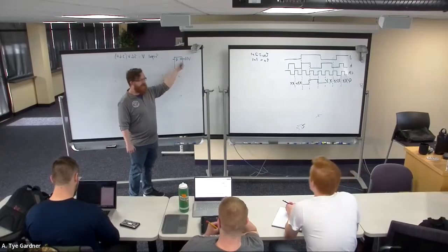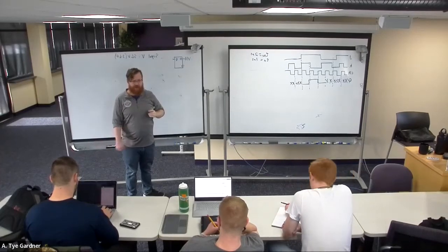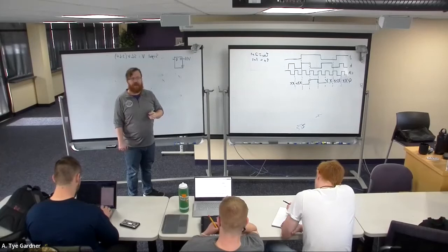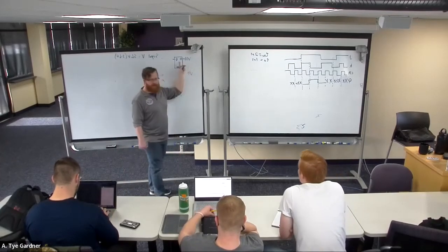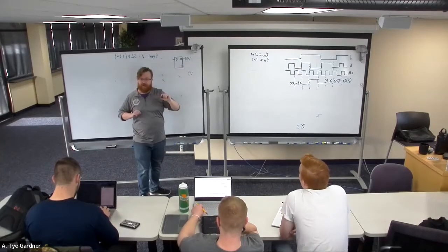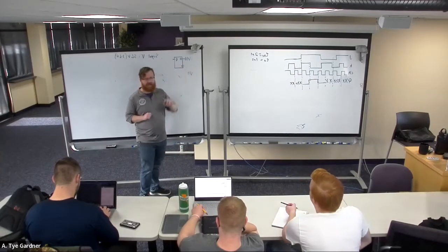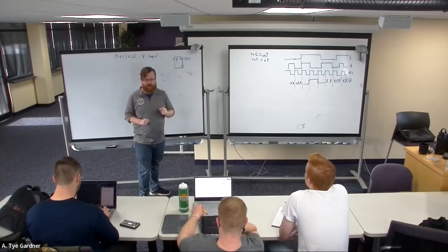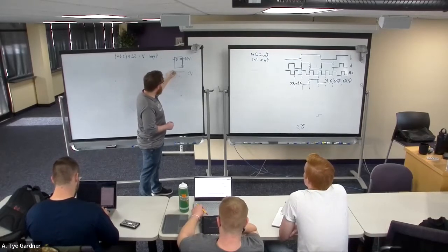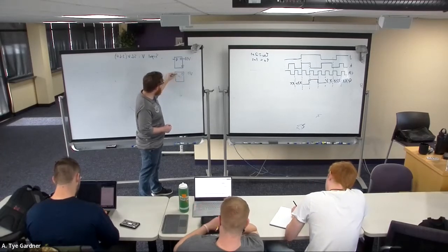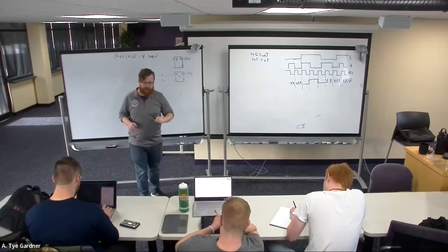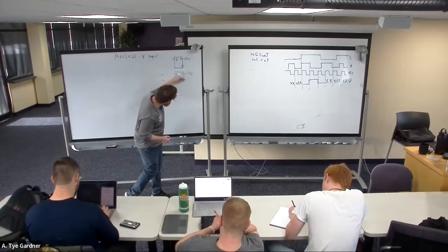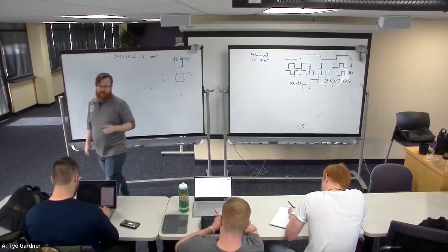Then the Q will save whatever V at 0 is at the falling edge of the clock. If I want to save V at 1 as well, I can't plug V at 1 into the same flip-flop because that's dual driven, right? That'd be 0 and 1 telling this flip-flop to be 2 different values, which is a problem. So we take another device, we call it D, Q, clock. There we go. This is now a register.